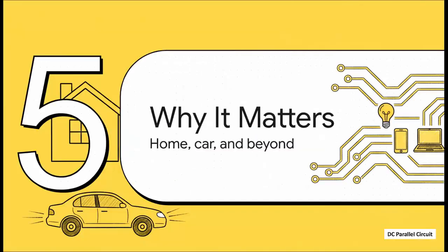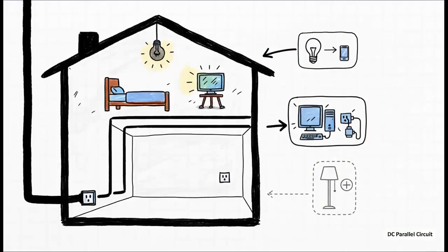We've covered the what, we've covered the how, but now it's time for the most important part, the why. Why do we even bother with all this? Well, it turns out the properties of parallel circuits are pretty much what make modern life possible. And boom, here it is, all tied up in a neat little package. Components operate independently. That is our light bulb example, right? Every outlet in your house provides a consistent, steady voltage. And you can easily add more stuff to the circuit.